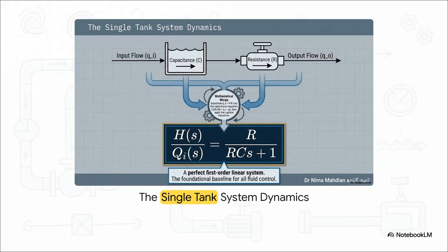Moving right along to Section 3, Single and Interacting Tank Dynamics. Let's bring it all together for a single tank system. Your input flow hits the capacitance to fill up the tank, and your output flow is restricted by that resistance we just talked about.